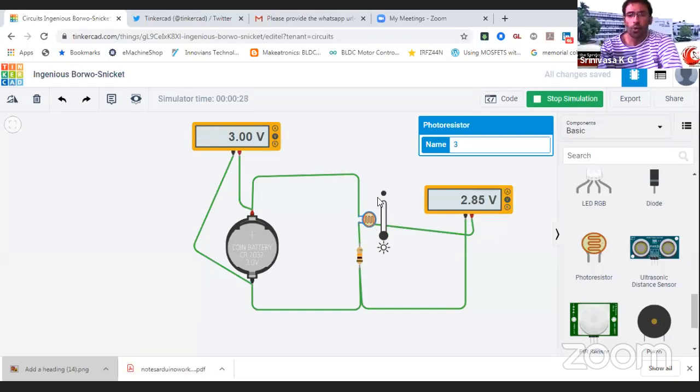So according to the deflection of this resistive type sensor, we have converted this deflection into voltage. That voltage we can read in our microcontroller, because my Arduino understands the language of voltage. So whatever sensor we are using, we have to convert its signal into the format of voltage. Only then will we be able to interface the sensor with Arduino.